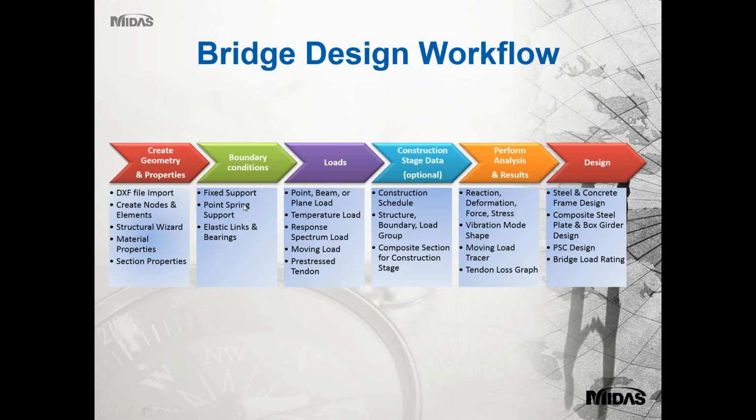The design workflow that we follow in Midas for any kind of bridge involves creating geometry first of all and assigning properties. Geometry can be either created within the software or you can bring it from AutoCAD files, basically the DXF file format.